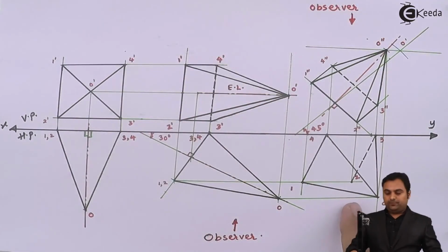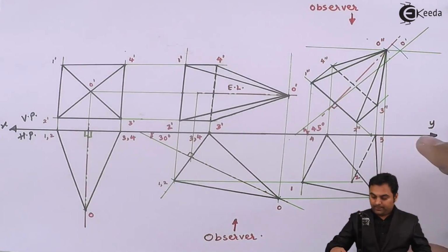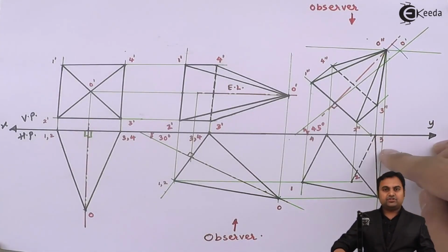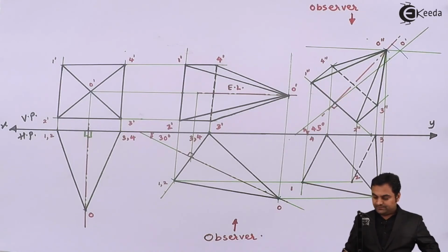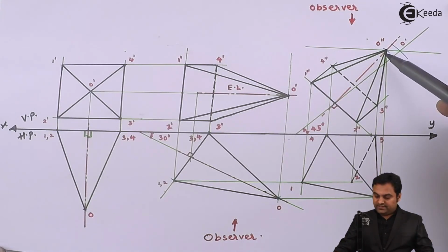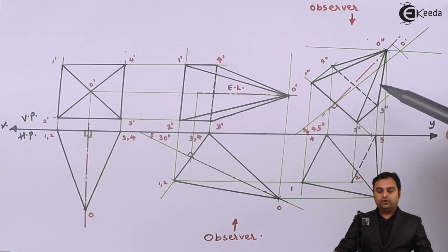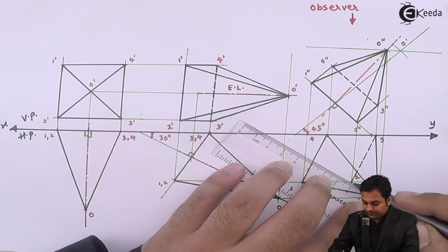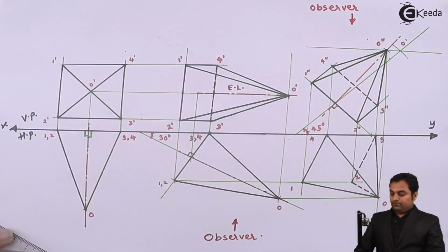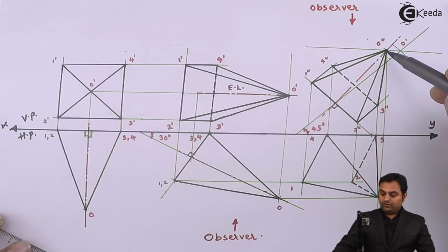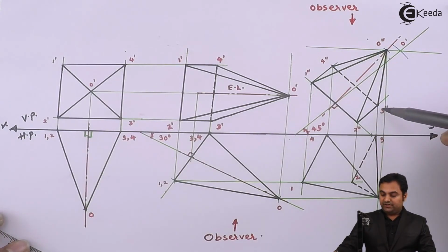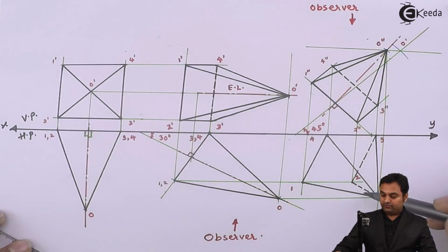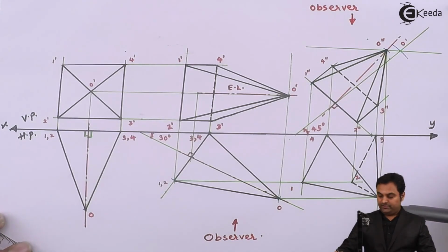So now, after projecting this pyramid, now getting the edge 3 to O, next, this edge which is O to 2, that will also not be visible to the observer, so that will be hidden. It means this triangular face O, 2, 3, which is O double dash, 2 double dash, 3 double dash, is going behind the observer, so that face is not visible.